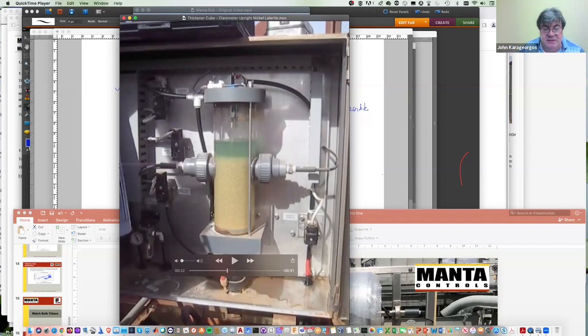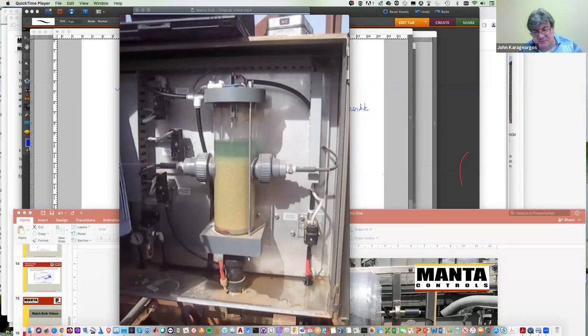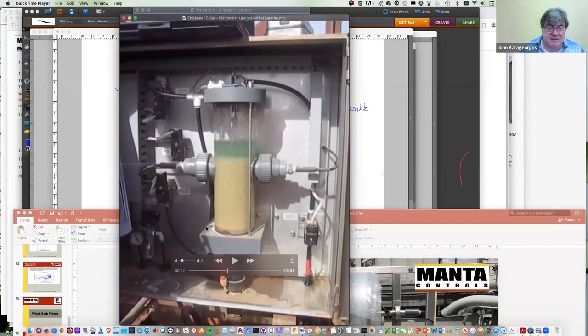And so the longer you can leave the flocs compacted at the bottom of the thickener, which is residence time, the more they're going to compact and you get a decent underflow density. The rakes also play a role, right? There's something else the rakes do. So leaving the flocs to form the bed in the thickener as long as possible also allows the rakes to do something to them, which then gives you a nice density. So being able to measure these interfaces is really important.